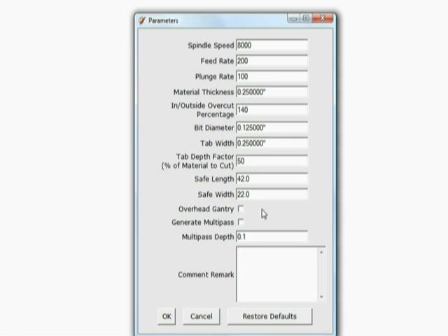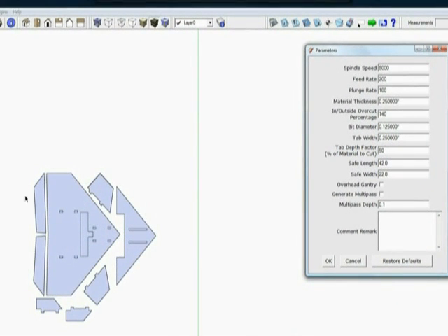And PhlatScript was set up so that if you're cutting around the outside of a part, like around the outside of an elevon here, the bit would travel in one direction. The goal was that on one side, your finished part would have a nice, clean, sharp cut, while the waste area would be the rougher side of the cut. The direction of travel complemented that, so that your finished parts look nice and sharp and clean.